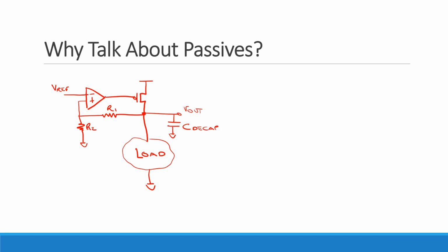Okay, actually, this is a great example. I like this one now. So you said you wanted this to basically control the ratio between the input and the output. So what you're hinting at is that the gain is going to be set by something about those resistors. So in terms of building those resistors, what would you care about from the standpoint of the gain? What's setting the gain, and therefore what do you want to make sure works well? So it's the ratio of the resistors that sets the gain, right? That basically means you really want resistors that match, right? Okay, very good. That's one thing that we're going to spend a lot of time talking about. What else might you want from those resistors in this exact context here?